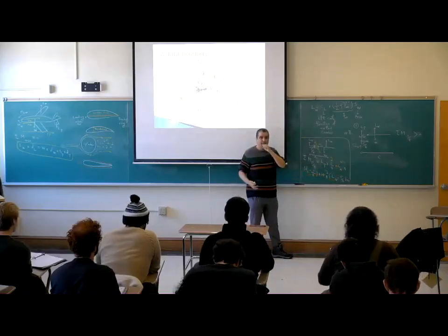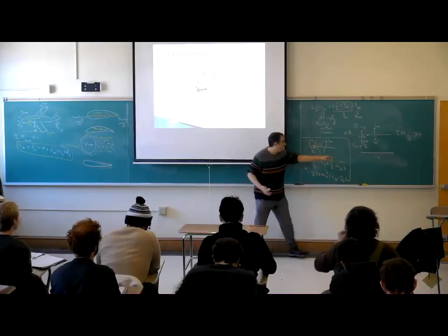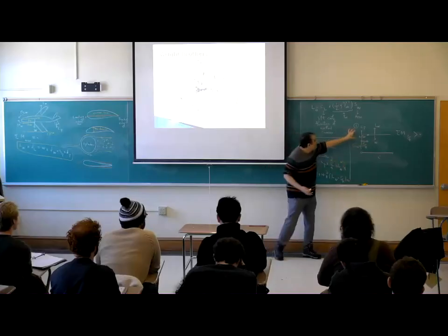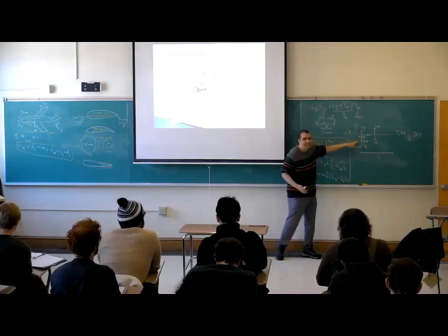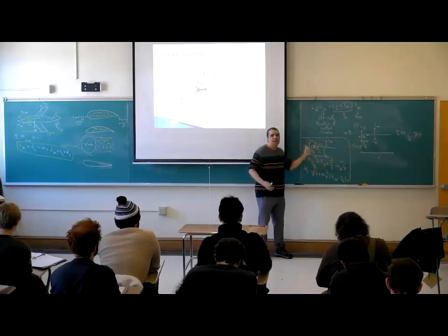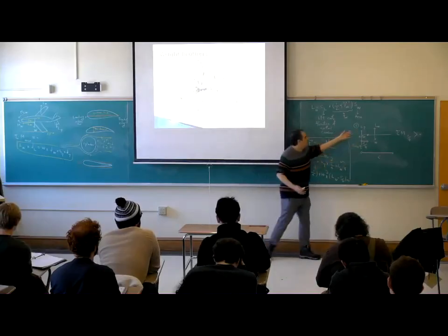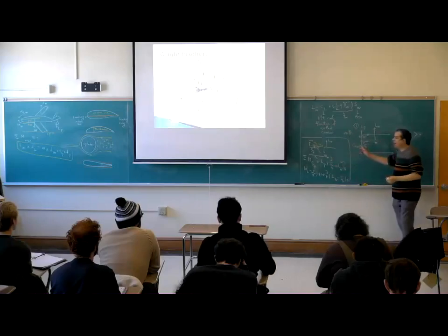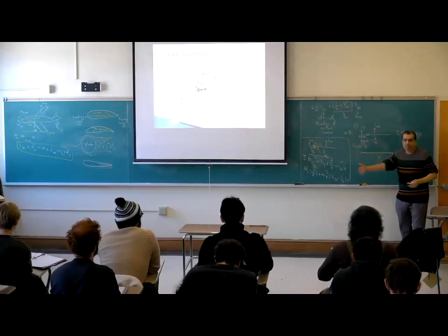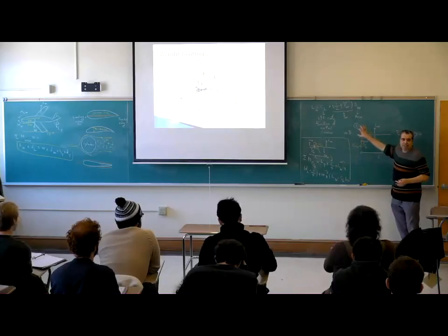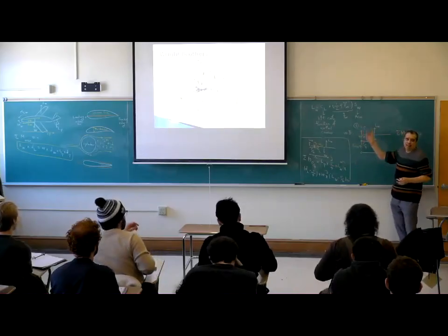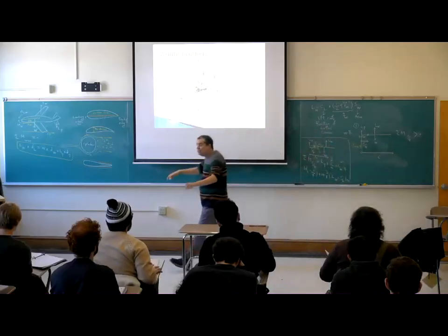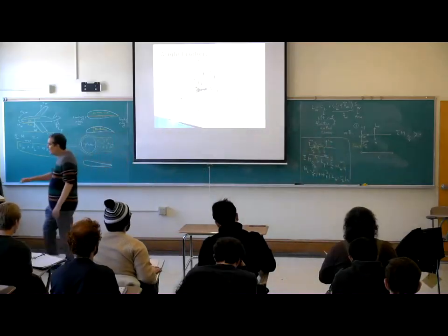Right, negative lift. I should reduce this lift such that the net of this plus this is the same as the original tail lift. For example, I had 100 tail lift here. I have a gust which creates 20 equivalent lift. So I should make it 80 from 100. So they should reduce the lift of the tail.